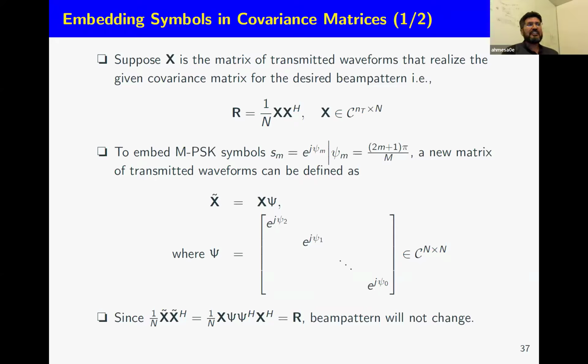I think here, how we suppress jammers: we transmit some waveforms that are unknown to the jammer. In the conventional system, we transmit a pulse and we don't encode those pulses. Here we encode those pulses.